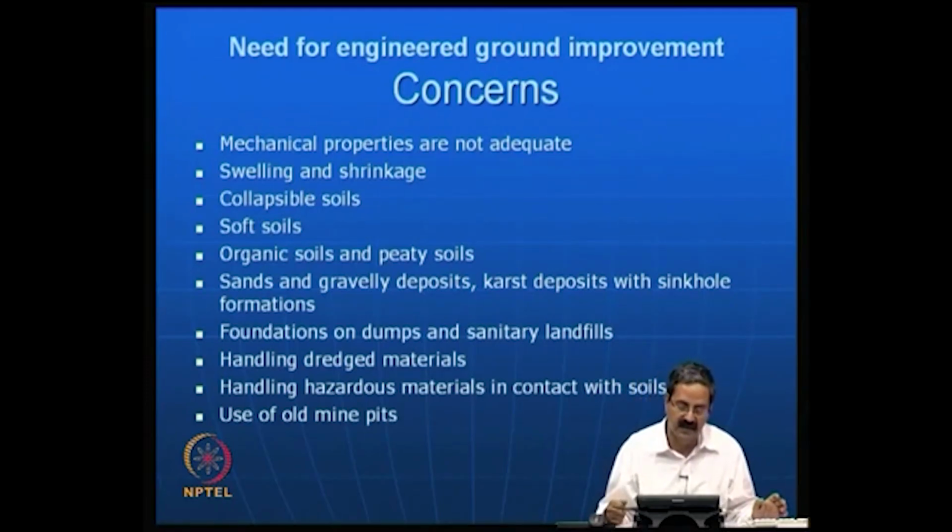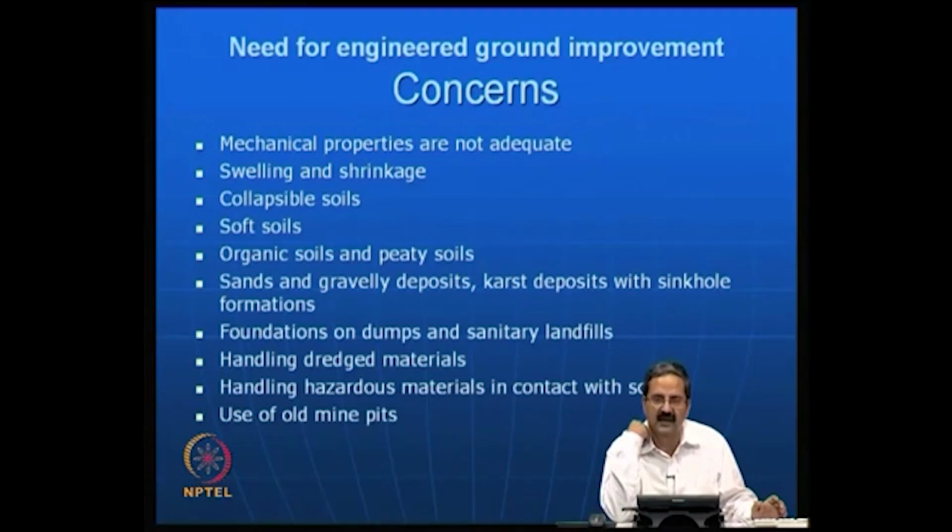In fact, dumps are waste material dumps, but sanitary landfilling is a scientific landfilling done in some places. Of course, in India it is just taking up in a big way in recent years with the Ministry of Environment and Forest's vigilance. But even with landfills, after some 20-30 years, when all the landfill gases and leachate are completely removed, then the landfill becomes inactive, and you would like to use that area for construction of buildings. You should be careful because these landfill materials are very complex, as I just mentioned, and one needs to really stabilize them in a proper manner before you use them for engineering applications.